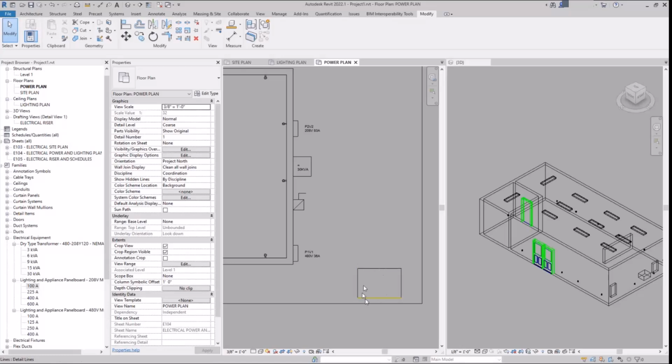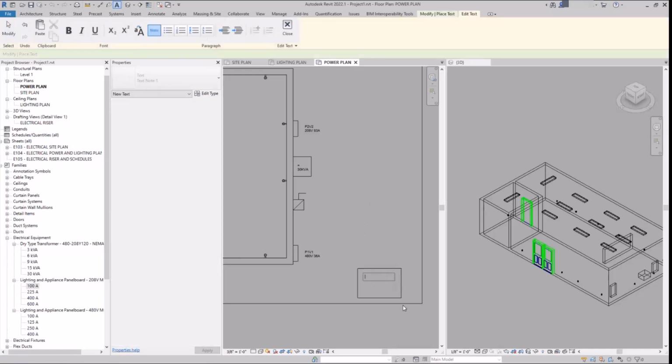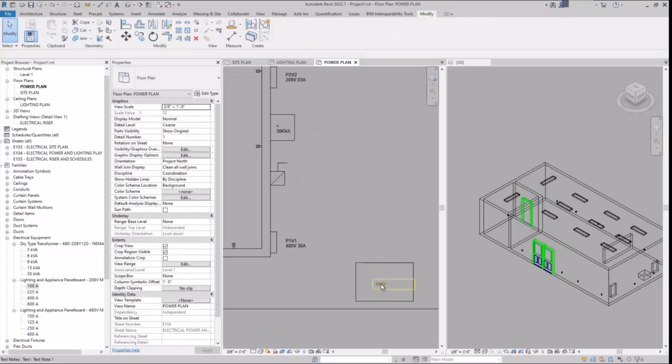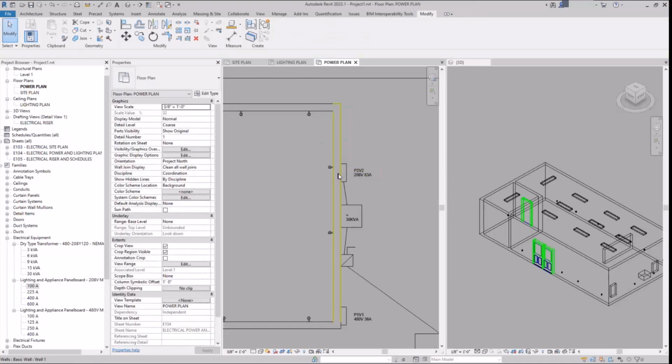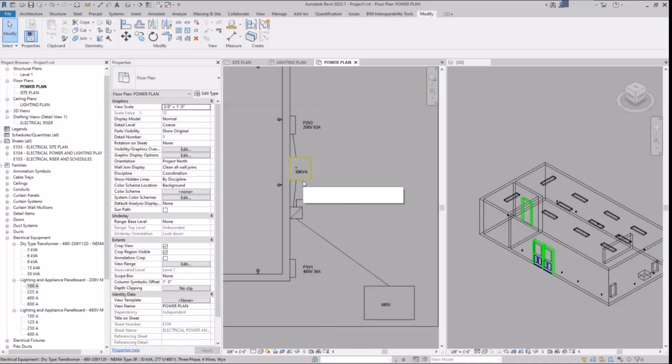All right. So if I have a utility transformer and everything on site is 120 or 208, literally nothing else is 480, and this thing only pushes out 480 volts because it's been there for years and years, and the owner doesn't want to change it, what I would do is take this 480 volt, hit the disconnect, from the disconnect feed the transformer, and from the transformer feed that. And from here, I would feed all the loads. Oh, like a new transformer, a 208? Yes. Okay. Yep.